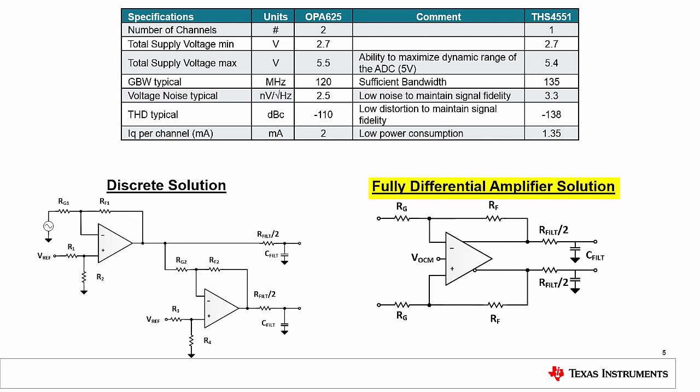The THS4551 is a fully differential amplifier that can not only do differential to differential signal conversion, but can support single-ended to differential conversion. We will explore which configuration offers the best performance for the precision ADC through theory, calculation, and simulation in noise, stability, THD, and settling time. But first we must select the resistor values for each configuration.